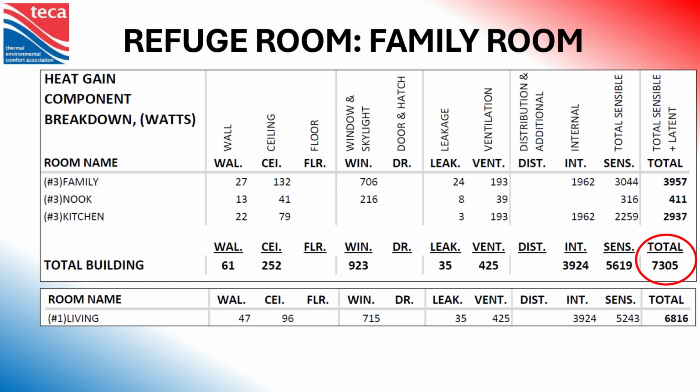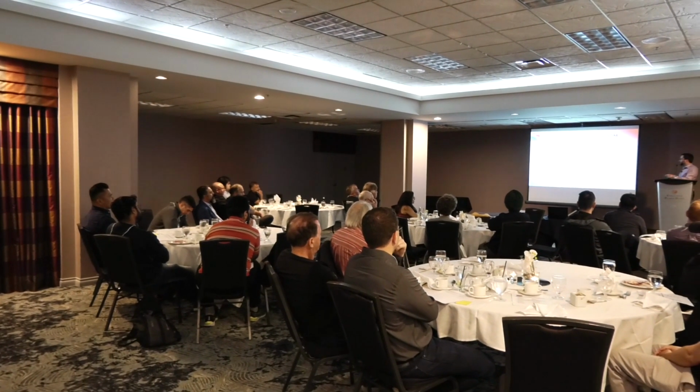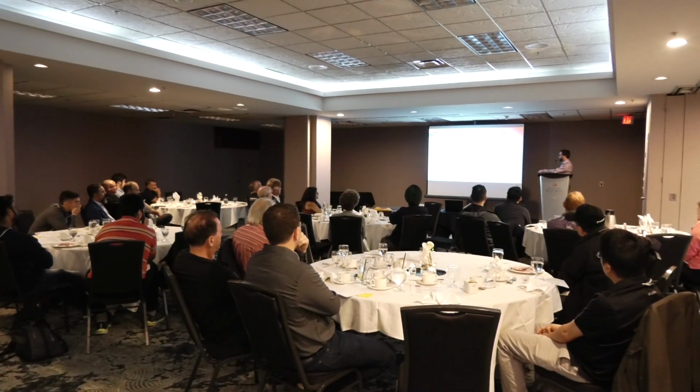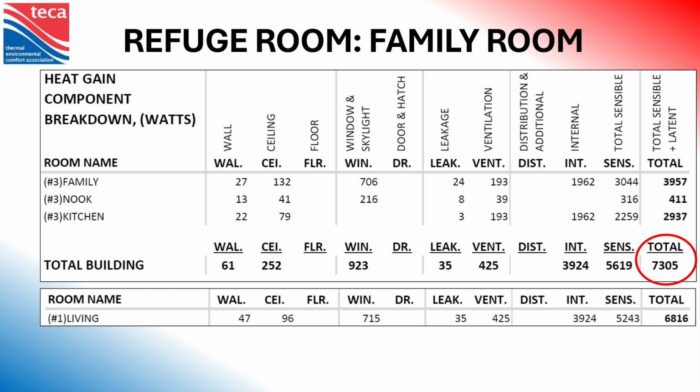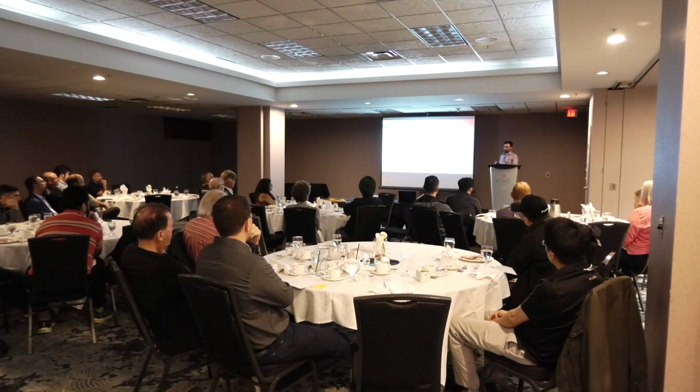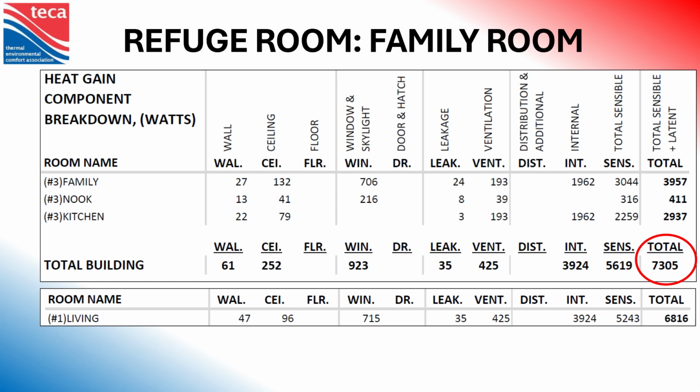So increasing them, doubling them, is still not a huge gain, because so much of it is coming from this interior load. Our windows have gone up, and if you look at those 3 rooms, you'll notice there's a lot more window space there, but they're all pointed north. So that's something to consider too, the orientation of the refuge room. A north facing room is always going to have a lower load, especially on the windows.